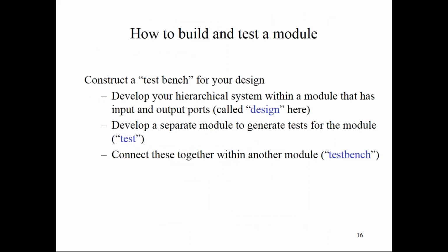So next is a test module. As I said, if I want to check a design, there are two types of testing possible. One is directly feeding the input inside the simulator. That way we are able to check the inputs. But in the case of multiple inputs, it is complicated to check all of them. So I have to cover at least most of the input combinations. That's why I'm using the test bench or test cases.